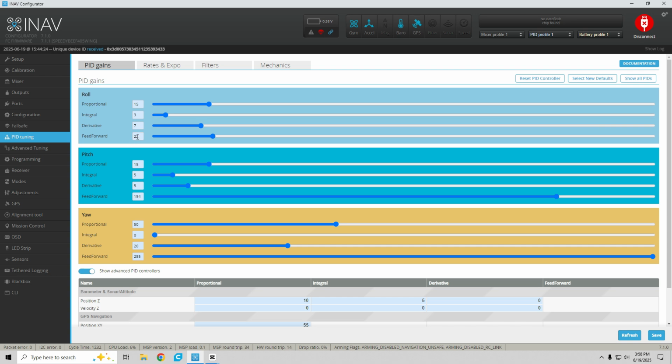I'm not sure what the stock setting was for feed forward, but these are what tuned out on my plane. Yours might be different. If you want more pitch on your first auto tune, I believe this is usually set at 80. I would suggest 125 or 130 feed forward on auto launch. This way it's going to give you more pitch authority when you're flying.